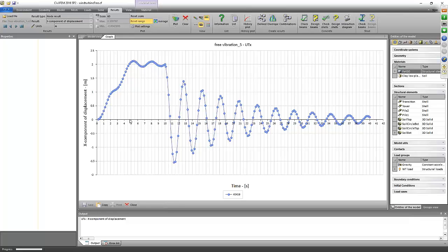Here you can see we applied the constant increment of the load, but even if we are applying a constant increment, vibrations start. Also, we keep a constant force, but there is a small vibration, and then at this point, at 10 seconds, we leave it. So this is the response. As we defined damping, the global damping of the model is just this reduction of the amplitude. If we don't apply any sort of damping to the model, this will be a constant amplitude of the wave.